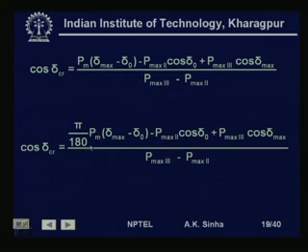So, it will be pi by 180, we multiply them and we get this value. So, when we are using radians, we use it like this; when we are using degrees, then we have to convert them into radians. So, this is how we can calculate the critical clearing angle.